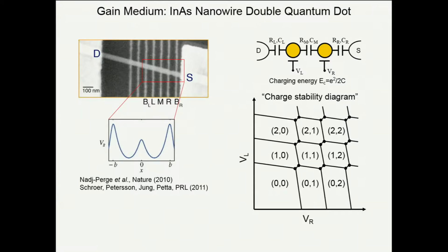In this case, it's made from a 1D wire. To get a current through the device, we put down source and drain contacts, and we can actually have a current flow through this device. And these gates that are underneath it are actually electrically isolated. So there's no current from the gates through the nanowire. These are just depletion gates that are insulated from the nanowire.